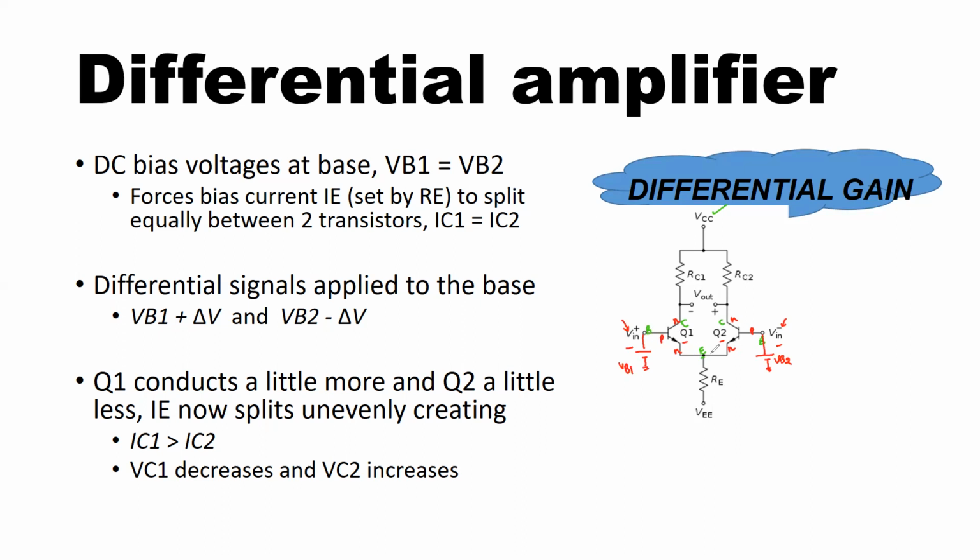Now, in order for this differential amplifier to work as an amplifier, my transistors Q1 and Q2 must be biased in the active region. In other words, this is the common emitter configuration, obviously. This is again the emitter degeneration resistance that is helping me provide stability against variations in the bias and the transistor intrinsic parameter variations due to temperature or some other effects or second order effects.